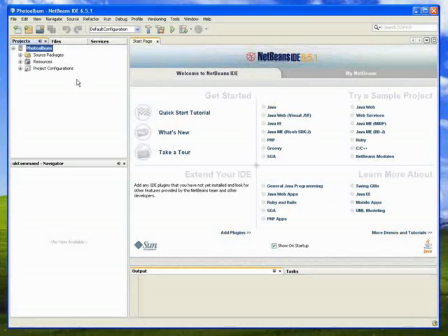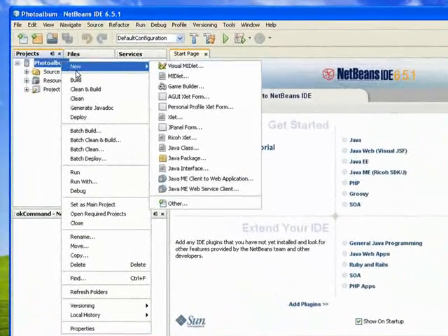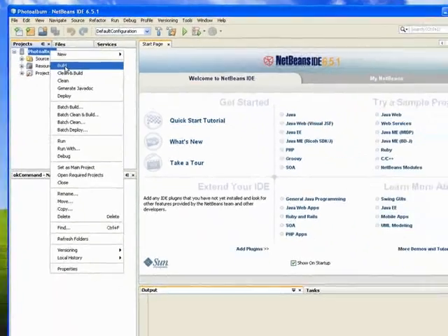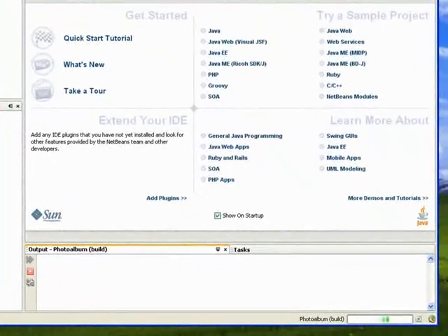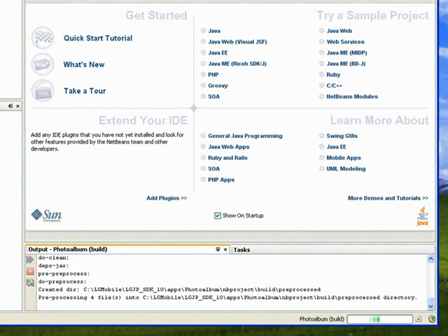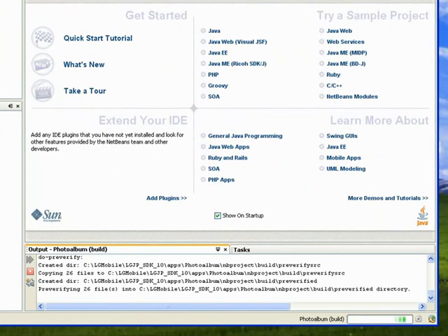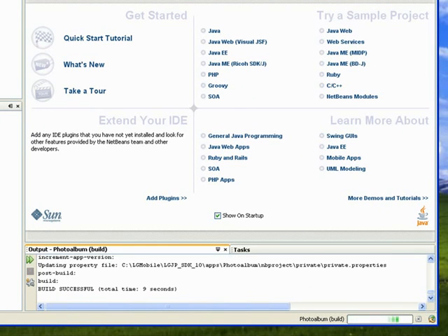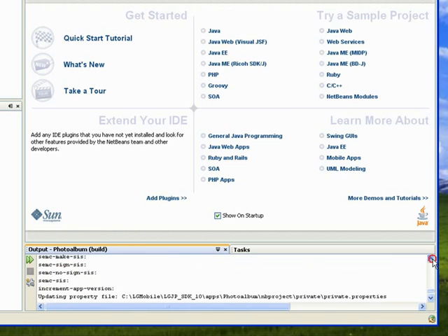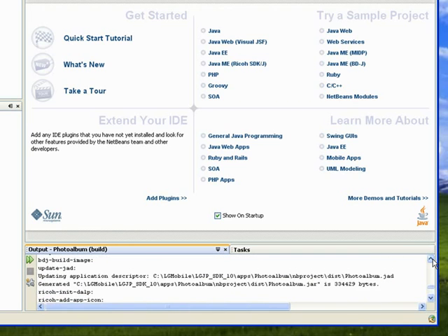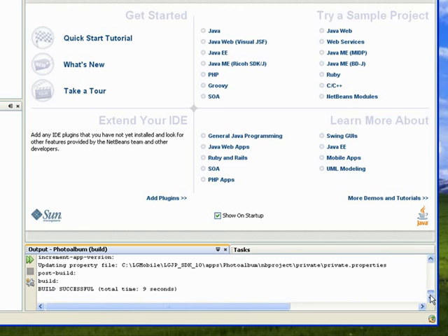Building project. To build the project, activate the corresponding command, and wait until the build is finished. The build operation will create application binary files. After the project is built, you can install the binary files onto the target device and debug the application.